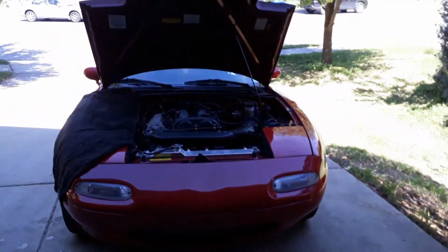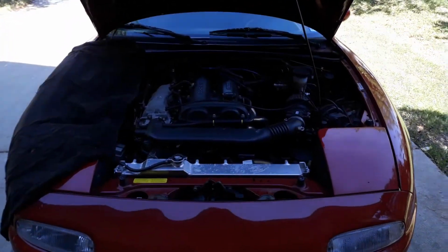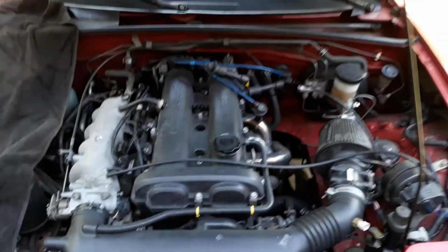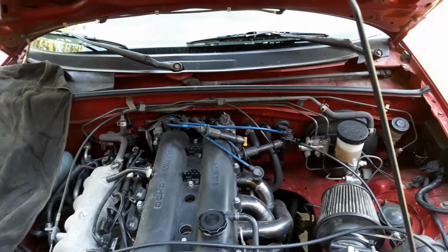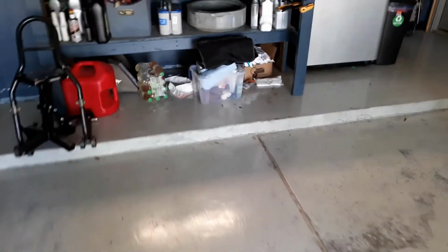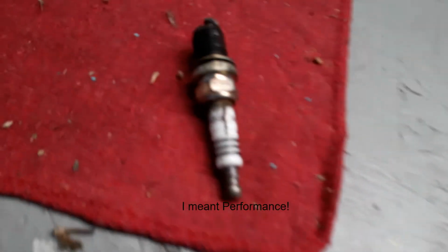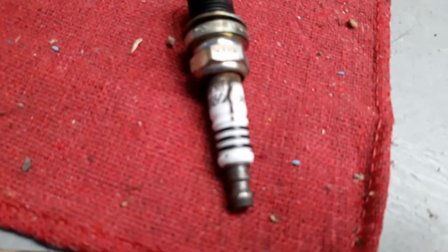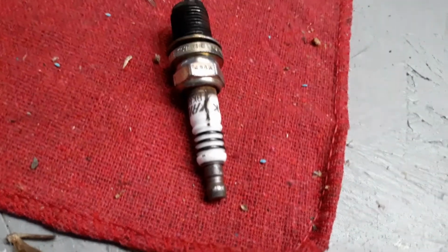And I got a Miata. This is perfect for today. This Miata has a misfire, so I'll show you what's going on with it. Air, spark, and fuel. There's my bikes. I'd play a bass solo for you, but we're supposed to be talking about engine repair. Over here on the table, this spark plug has a crack in it, so I believe that's my culprit. I got new ones coming, so we'll find out when they get here.